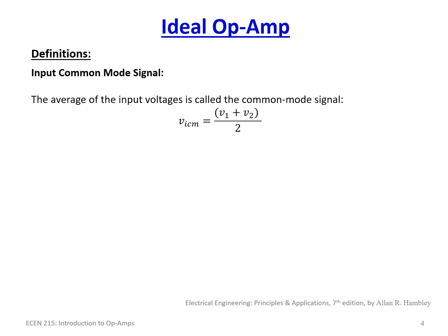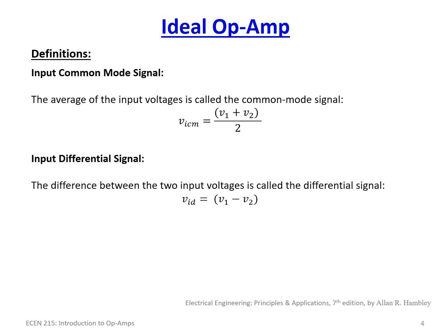In the end, you do not want any of the common mode to actually carry through. You're just looking at the difference between the two. Now, the differential signal is truly the difference between the two input voltages. Again, we have two input voltages, V1 and V2, and we're interested in strictly the difference between the two.